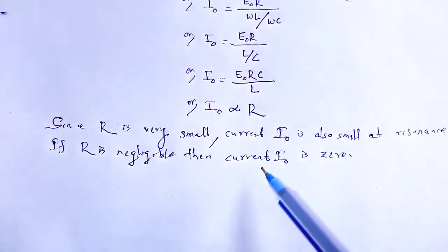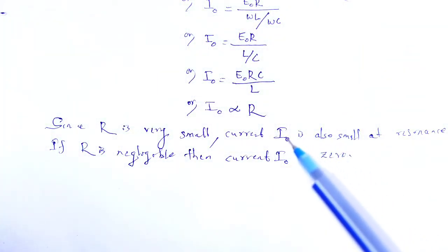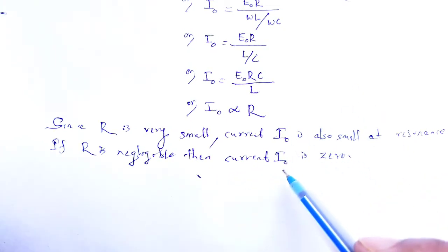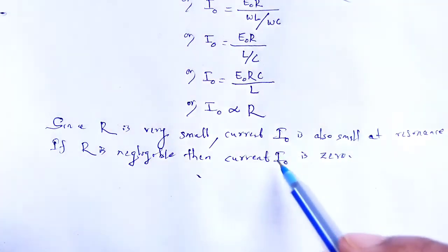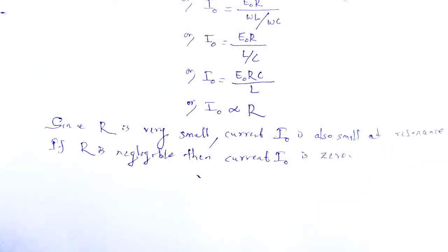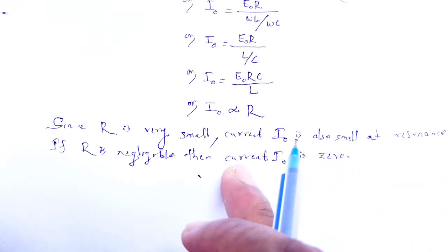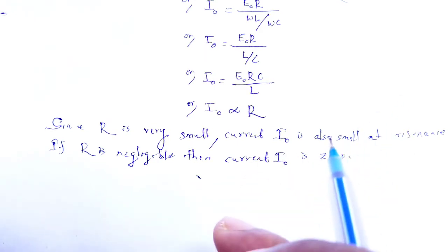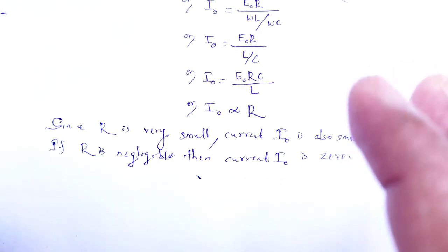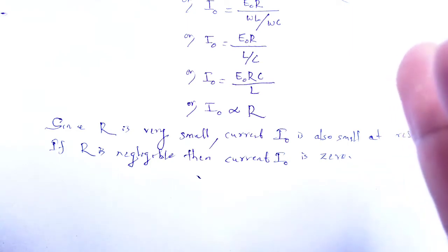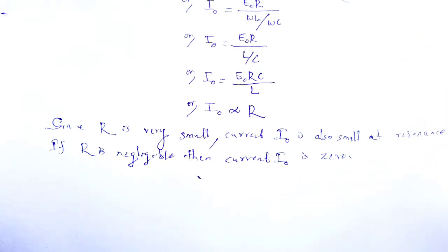Look here, in case of parallel resonant circuit, that does not allow current of the same frequency as the natural frequency of that particular circuit. So the parallel resonant circuit may be used to suppress the current of this particular frequency out of the current of many other frequencies.